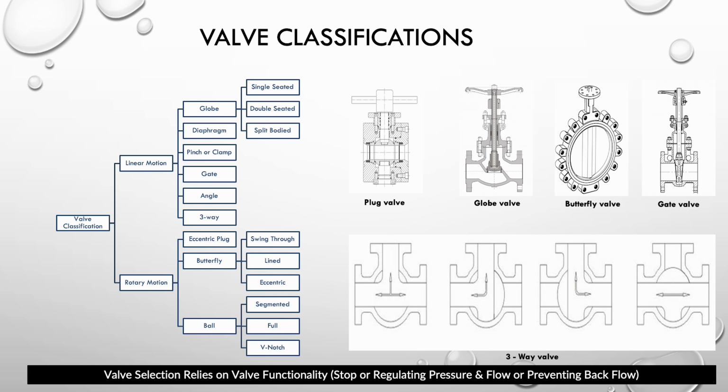Gate valves are not recommended to be used as a regulating valve because they are going to get eroded pretty badly. They are not designed for it. If you look at their design, the problem with the gate valve is they are very restrictive. They are literally getting head-to-head collision with the fluid. So, given time, they are going to be eroding. They don't have this sweet, smooth change of momentum around them like a globe valve would.